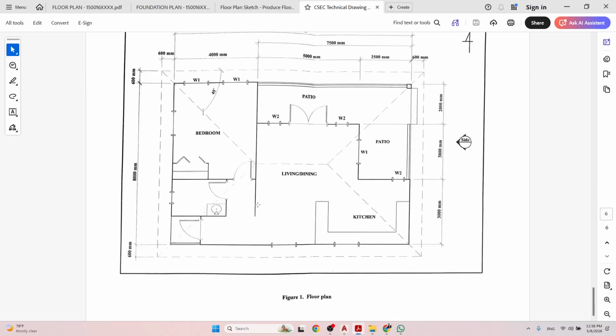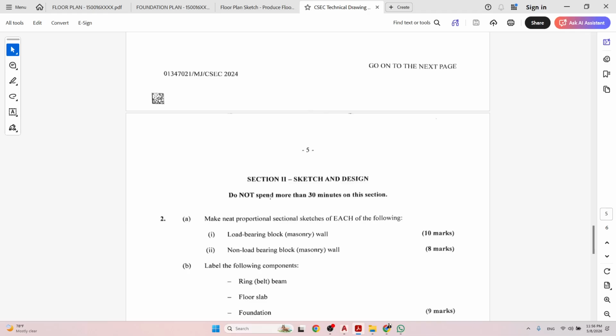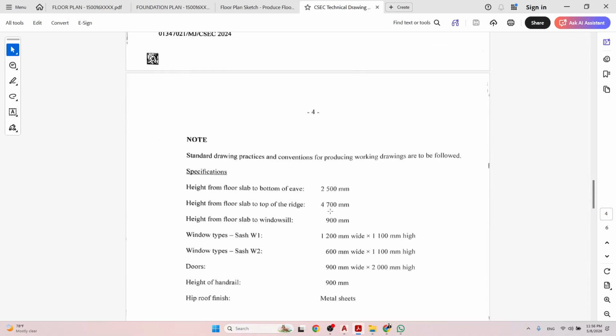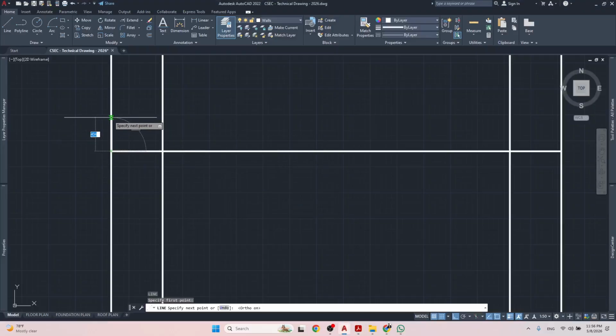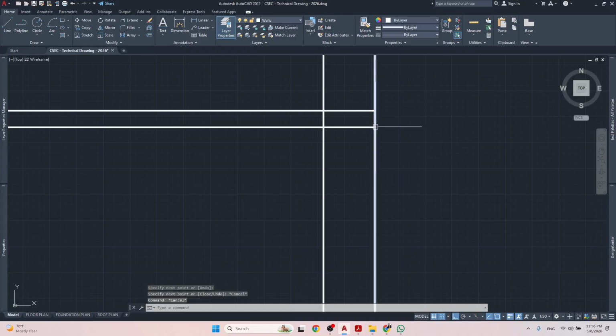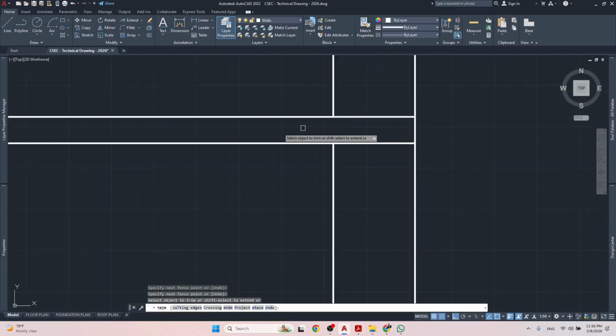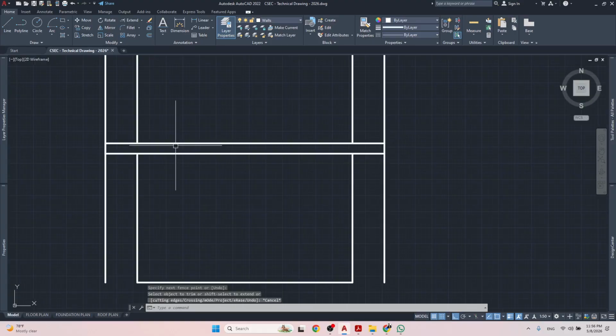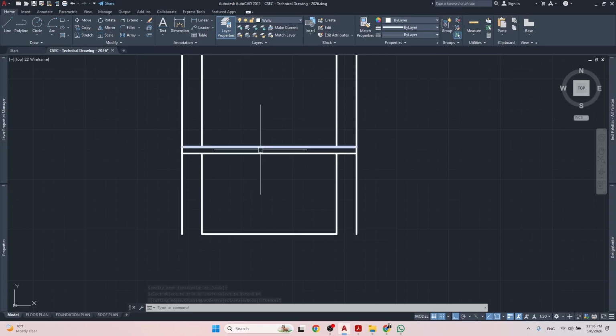I don't know if the specifications mention the thickness of the fascia board, but the fascia board is usually about 6 inches, 8 inches. We have been using 8 inches, so that's 200 millimeters up, and then I'm going to come across all the way across. All right, and then I could just trim out this in here. All right, so that's my fascia board. This line just represents my overhang. Now I know where my roof is. I don't need it anymore.